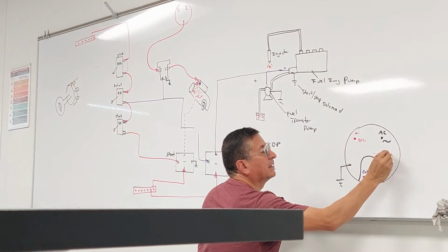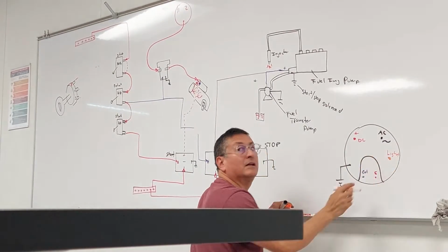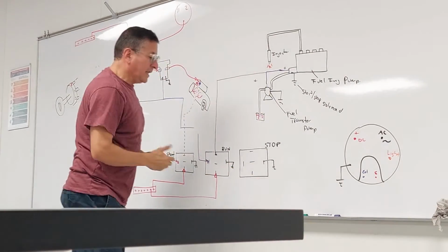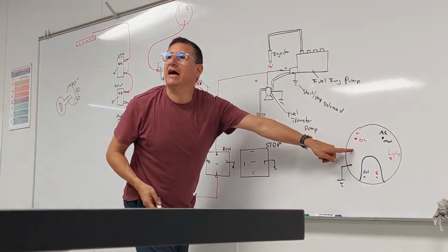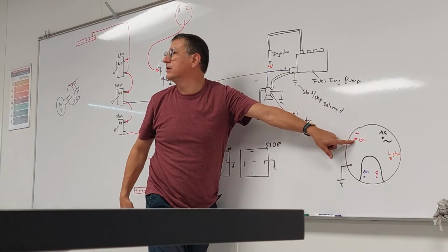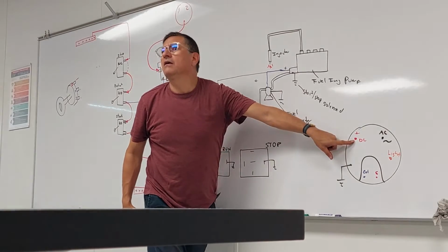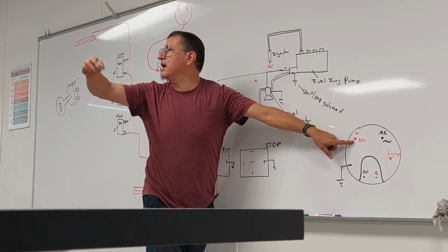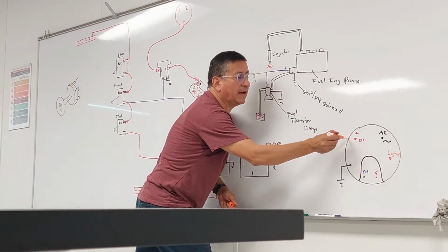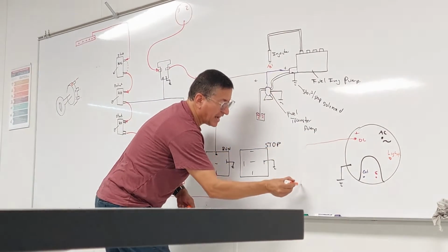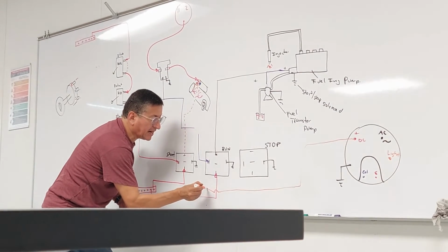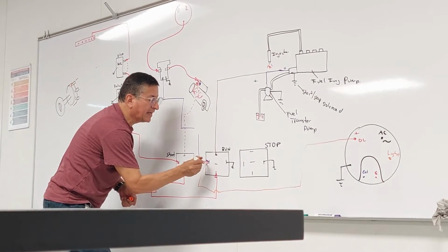You remember that alternator? The Motorola, correct. Okay, look, from the output of the alternator, how much is the voltage when the alternator is running? 12? 13, 14. In between 13.6 and 14.2. No? And what is the color of that cable normally? Orange. I bring my orange here, here, here, here, here, and here.